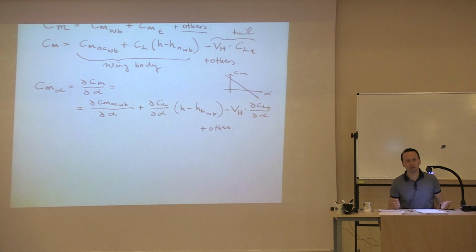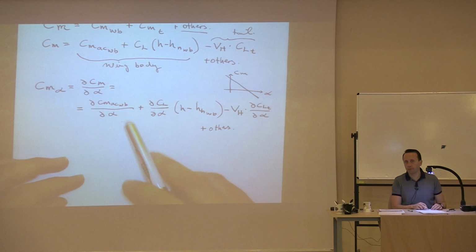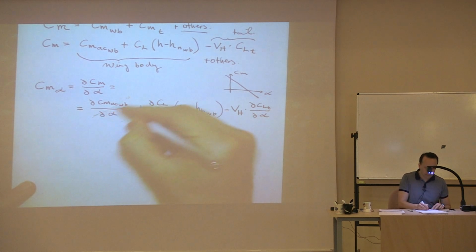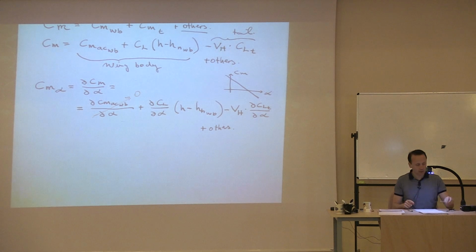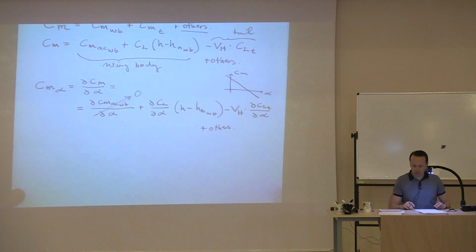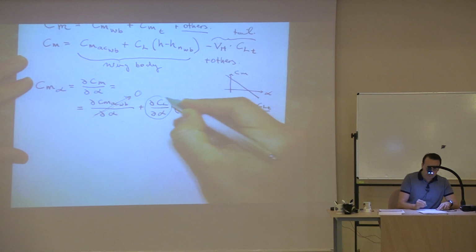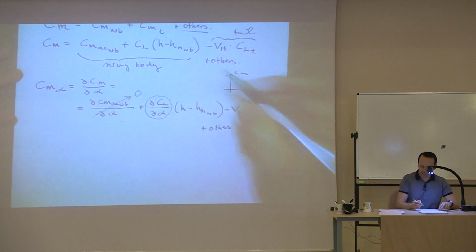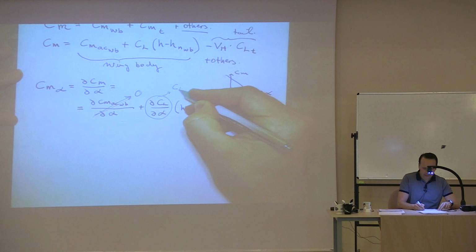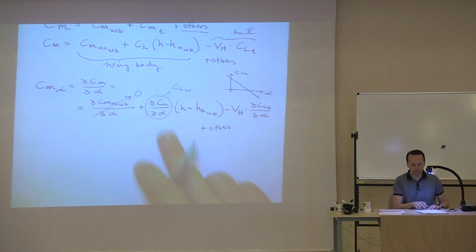So here you see the benefit. If this was not at the aerodynamic center, then this term would still exist here. So this goes to 0 because, as I said, the aerodynamic center is, let me use the green one, equal to 0. This is del Cl alpha, basically the lift curve slope. So that's del Cl alpha of the airplane, of the wing body.